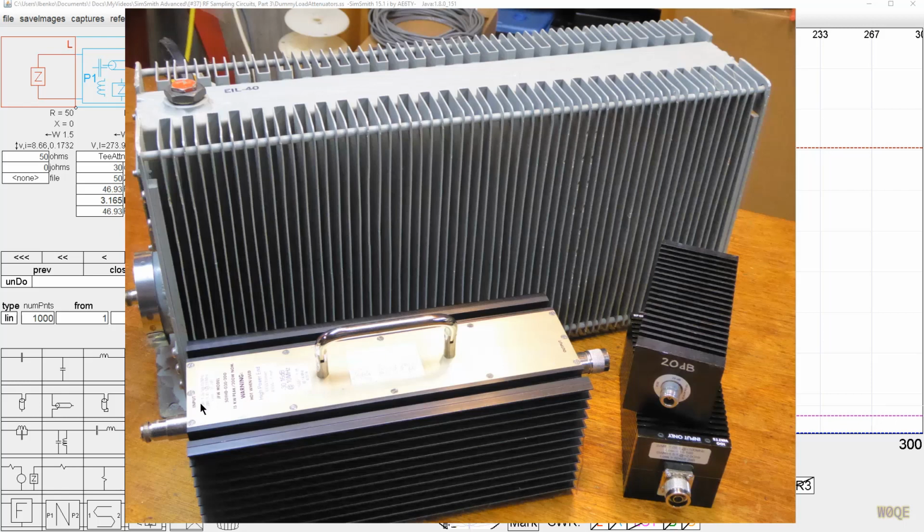on the output side. However, if you buy attenuators like this at a swap fest, a lot of times the markings are removed from them. And notice there's 4 shown here, but 3 of them have a female input connector on them, and 1 of them is a male input connector. I've got about 12 or 13 of these things, and it's split in terms of which connector is the input connector. Most of the time they're female, about 2/3 of the time female and about 1/3 of the time male. But without knowing via marking which one is the input, you're in deep trouble and you're just guessing. So anyways, we can analyze these in SimSmith quite easily.